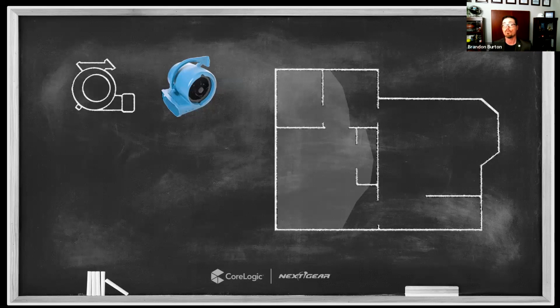There's some places I wouldn't want to put it, like on top of a hardwood floor if I can avoid it in case the dehumidifier leaks, or right in front of an air mover so I'm blowing air at the front of the dehu. But aside from that, it shouldn't matter where the dehumidifier goes. If I install my air movers properly, then no matter where the dehumidifiers are in the chamber, I'll be mixing that air throughout the space and getting a balanced condition throughout the chamber.